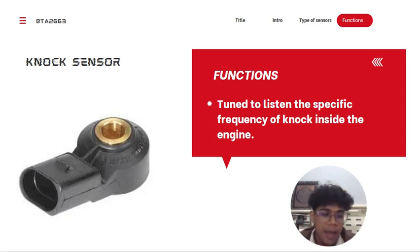Next is the knock sensor. Knock is an abnormal combustion inside the engine. If it is strong enough and if it persists long enough, it can cause catastrophic engine damage. A knock sensor is essentially a microphone tuned to listen to the specific frequency of knock inside the engine. This frequency depends on the engine, but largely it depends on the bore and stroke of the engine.